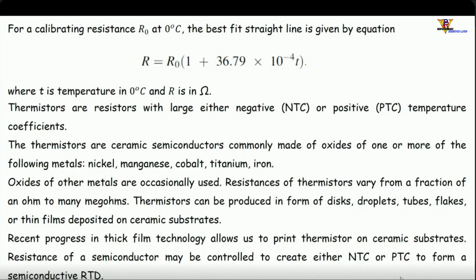So if temperature is increased and the resistance of the material increases, it has a positive temperature coefficient, and we can control it. Control means, in the sense, we can sense. So if there is variation in the temperature and we want to sense that variation, we can design a thermistor that has a positive temperature coefficient of resistance. By sensing that variation, we can sense the variation in the temperature. This is mentioned in this slide.